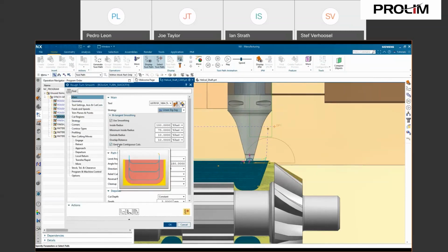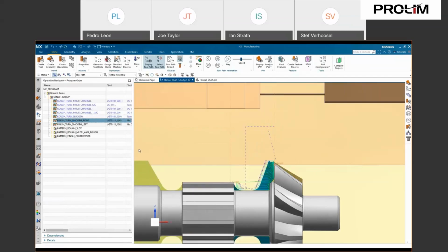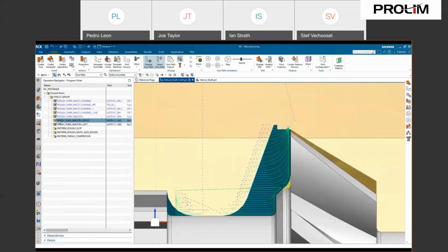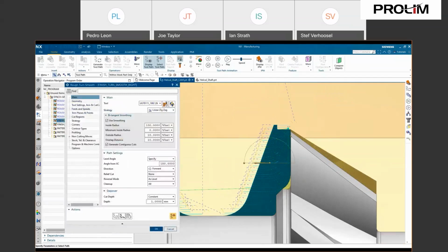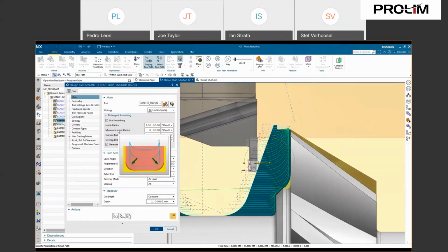In there, you can see there's some parameters that affect whether the engage and retract moves are put together in that contiguous cuts, whether the inside radiuses, and of course, as I said, because of this style of toolpath, we can really start to ramp the depth of cuts and feed rate up. Obviously, using that neutral RCMT tool, we can only get so far into the geometry. So I've now picked a multi-direction grooving tool just to show that it supports multiple tool types.